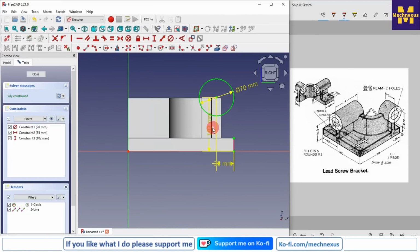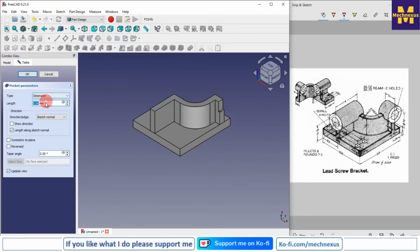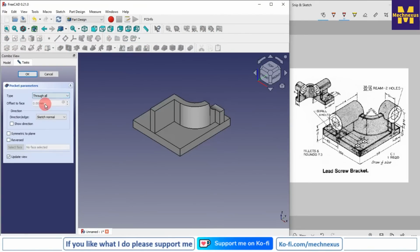If you want to see the dimensions, I move it outside. So it is a 35 from the edge, which is this one. Diameter is a 70, and height of vertical position we can say is a 102. So now I will close it, select my sketch, click on the pocket, and from here I will say through all.